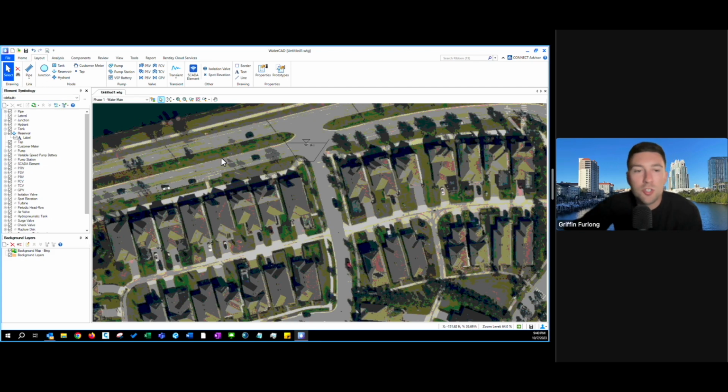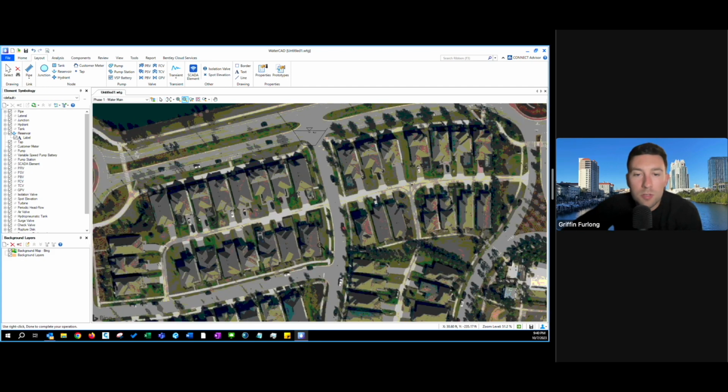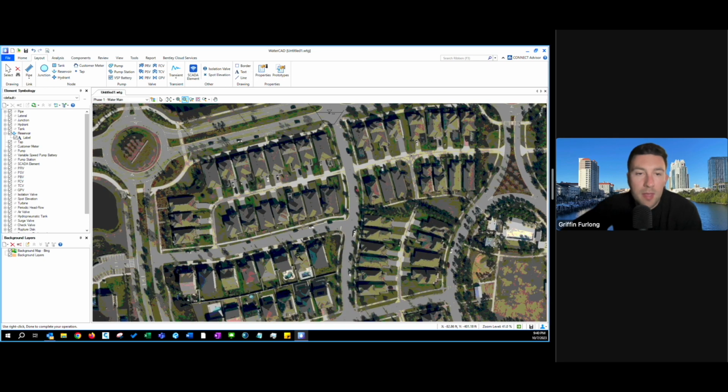And now I'm just going to start laying out pipe. So I want to zoom out here. And like I said, I wanted to build this thing from that reservoir and just hook around into this road. So let me grab my pipe that I have. Let me click that reservoir where our point of connection is. And you see how it's starting to draw? So one thing that I can do is I can go around and click around here, and I'll show you how this is all laid out.